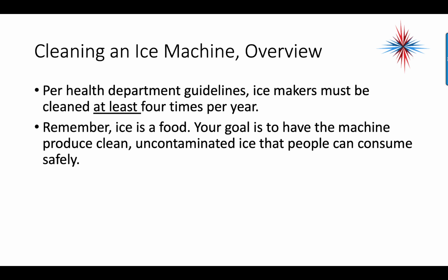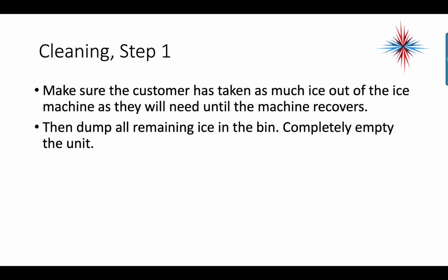So when we look at maintenance of an ice machine, per health department guidelines in most states, ice makers must be cleaned at least 4 times per year. And the place where the ice maker is has to have documentation to show it's been done. Remember, ice is a food. Your goal is to have this machine produce clean, uncontaminated ice that people can consume safely.